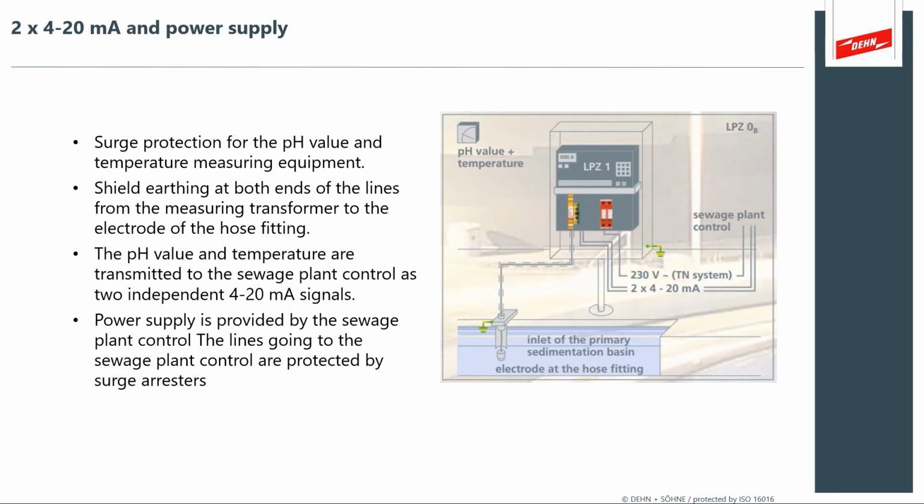Here we see a very similar application with the pH control systems. You're monitoring delicate chemical balances so that the organic processes of the water wastewater facility are properly maintained. And we can see that you have a combination of 4 to 20 milliamp type circuits in addition to AC power control systems as well.